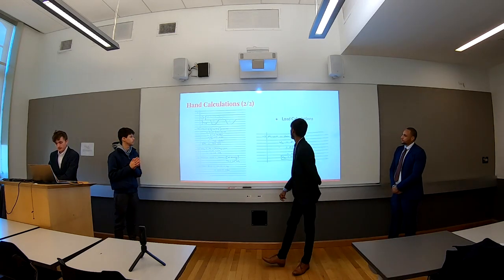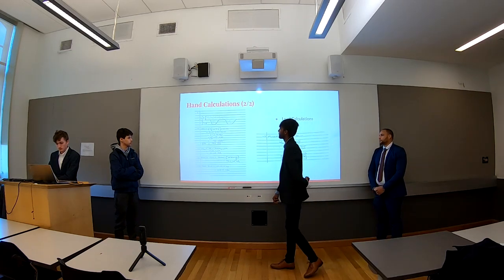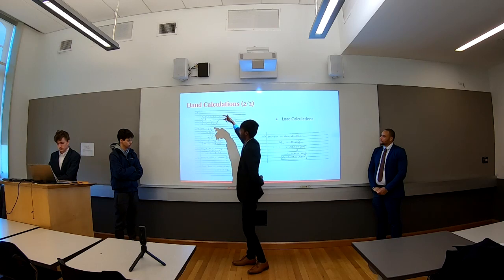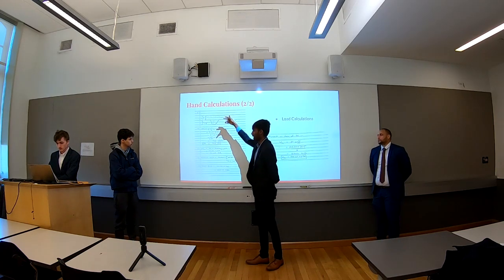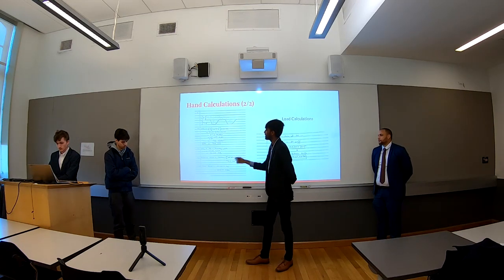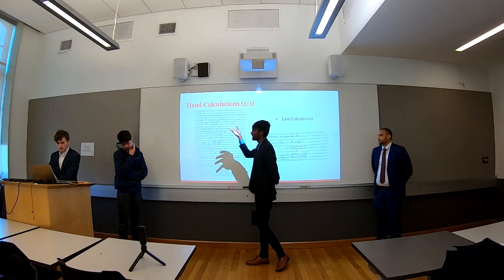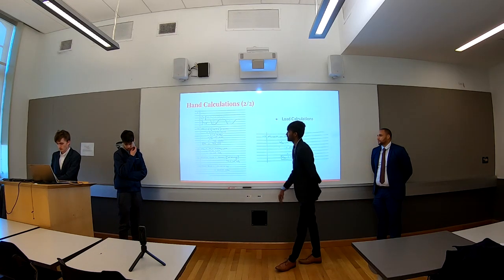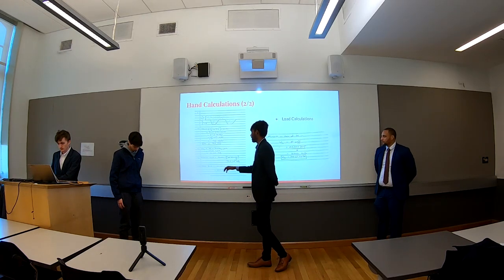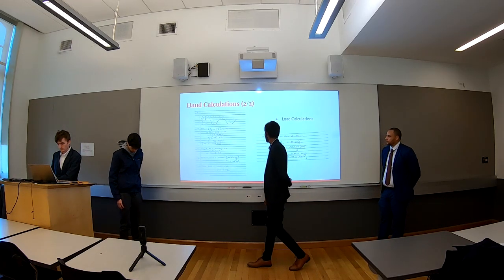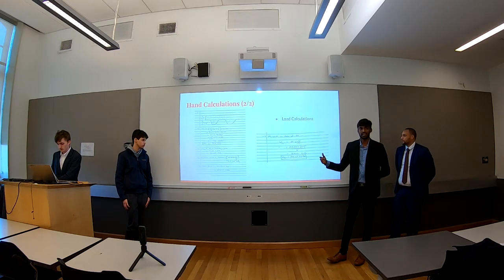We also did load calculations for the metal deck, and as we know, we have 4.5 inches of concrete, 3 inches for metal, and a half inch we added to account for the metal pieces throughout the section. So that's how we counted everything, and the total applied load we got was 627, and then we went over the moment, which we got slightly off from our ETABS result.